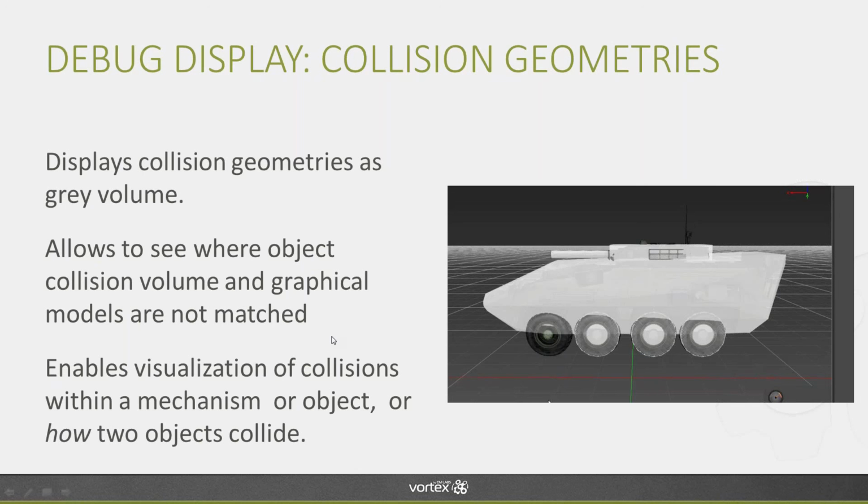So you can see those collisions within a mechanism as well, and you can then define the collision rules that you need to add to your mechanism. If we go back to our example of the forklift, for example, and we made a collision volume for our cabin, then the wheels are actually kind of recessed in that cabin. And if we make a simple prism for the cabin, then they would actually collide together unless you put in a collision detection rule, which is something that you could forget about when you're working on a lot of mechanisms at the same time.